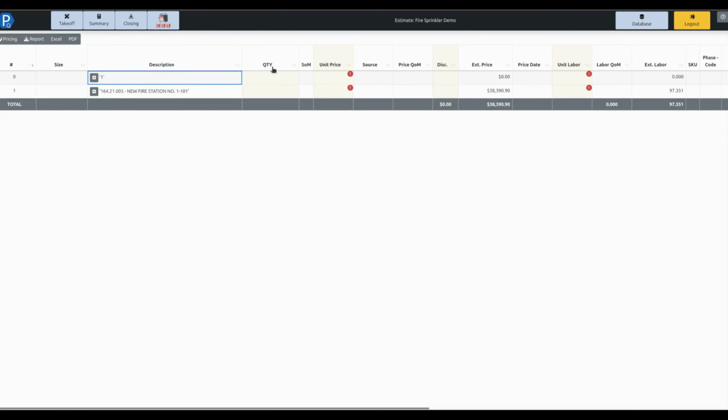When you group things, the quantity column unlocks here. So if you are doing, say, typical floors, hotel work, that sort of thing, where you have standard suites, if you take off areas within the platform to lay this out, you would have a standard suite A, for example. You can click on the quantity here and put a multiplier in. So if you had 20 of these, you could type in 20 there, and it would multiply out all of your quantities and then apply that for all of your material and labor pricing, allowing you to build very high value, complex estimates very, very quickly.